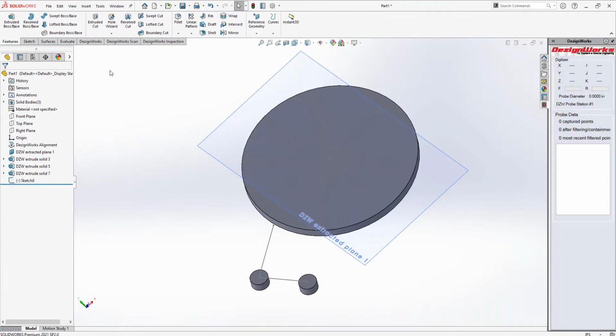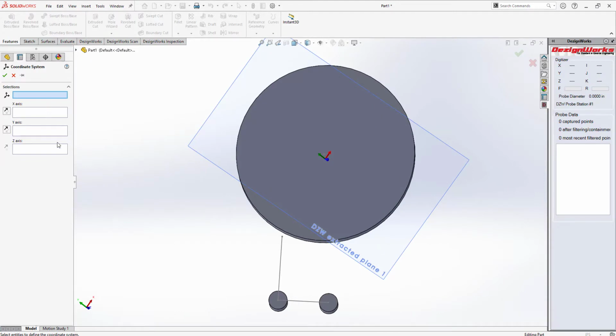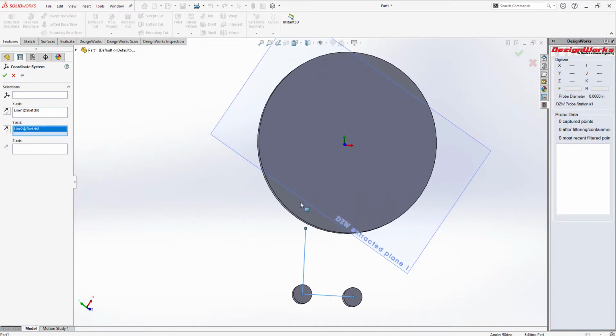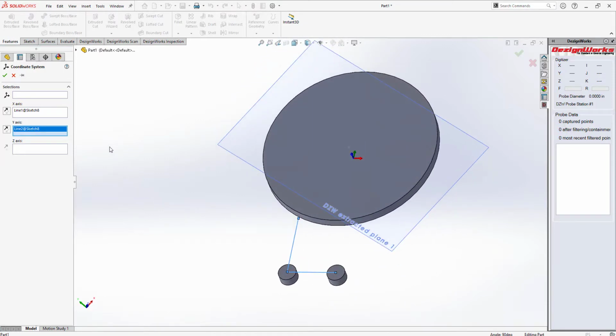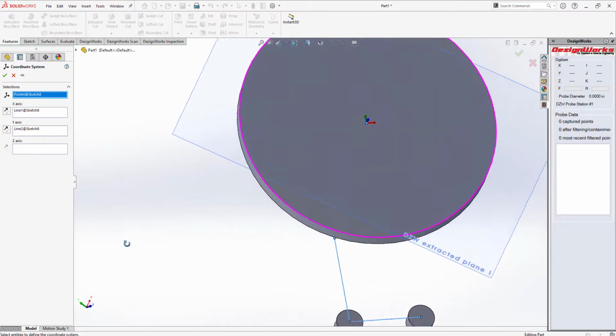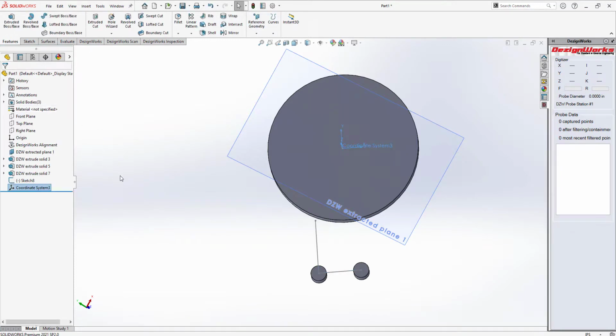So you go to Features, Reference Geometry, create a coordinate system. It wants to know origin, X, and Y. So you could simply do this if you wanted to. What's the X? You could pick this line. What's the Y? Now you have your little Cartesian coordinate system, but it still doesn't know where we want 0. So we're going to say it's right here. So you can see X, Y, origin's there now, and you actually build it.